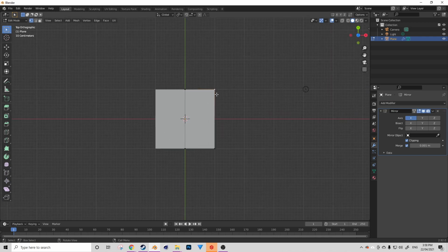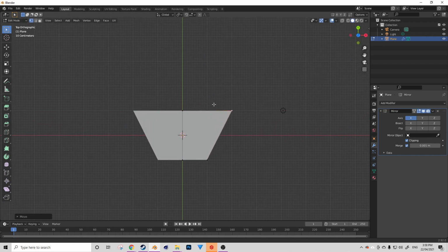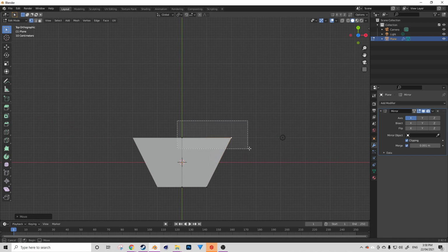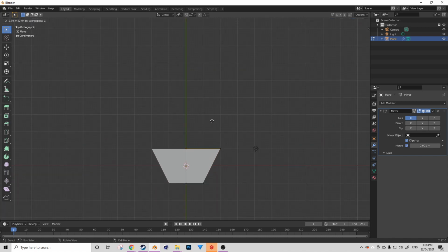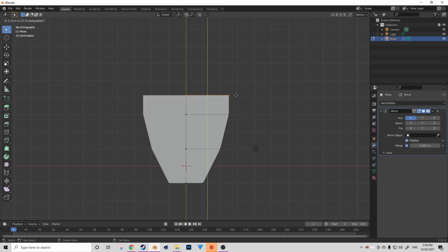Now we're going to create the basic shape of the top deck by pulling out these vertices. Remember, G for grab. Alternatively, you can use the move tool in your toolbar on the left-hand side of the screen. To extend the deck, select the 2 vertices and then press E to extrude. You can hold Ctrl to snap to the grid if you're in orthographic view. Then fix the shape of the deck so it's nice and curved like so. And now it's just rinse and repeat.